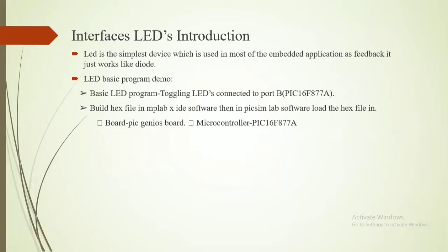So here I have taken an interface of an LED. We all know that an LED is the simplest device, used in most embedded applications as feedback. It just works like a diode. In this we have done a basic program demo, toggling the LED using Port B of the PIC 16F877A.